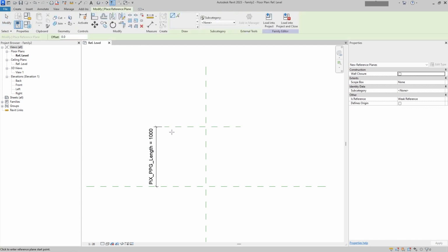Then we will add the thickness of the facing reference plane, then the thickness of the flange reference plane, then the end of the weld neck flange itself, and then we will jump to the inside diameter of the nozzle, the outside diameter of the nozzle, and the outside diameter of the flange.